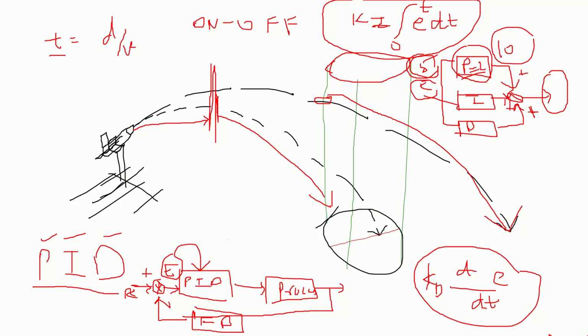Now if you try to link this with the example that I have just given, and employ a proportional controller in this particular case, you have a distance, and you have an error proportional to this distance. Using a proportional controller, you multiply E with Kp, the proportional constant. This is the output from the proportional block, and this output, E times Kp, will be fed to the process.